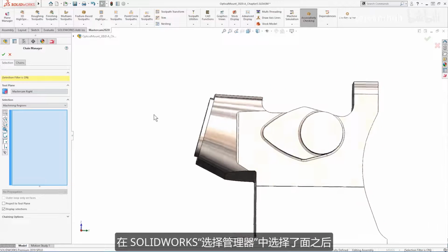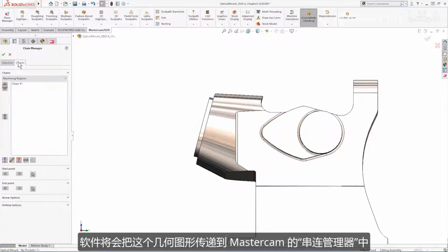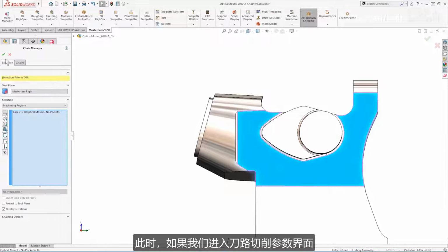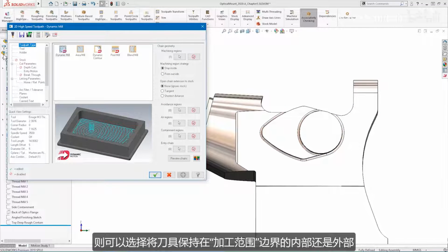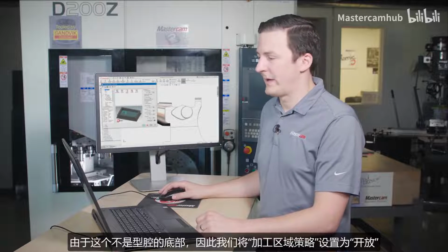After we're done selecting faces in the SolidWorks Selection Manager, the geometry is passed into Mastercam's Chain Manager, where it can be turned into a toolpath. At this point, if we proceed into the toolpath cut parameter interface, we can instruct the tool to either stay inside the machining region boundary or come from the outside. Since the face isn't the bottom of a pocket, we'll start with from outside.